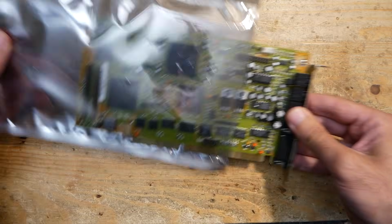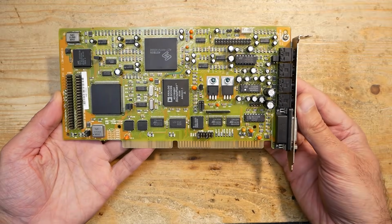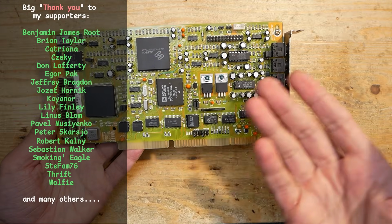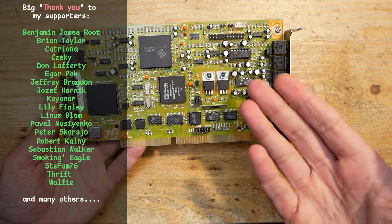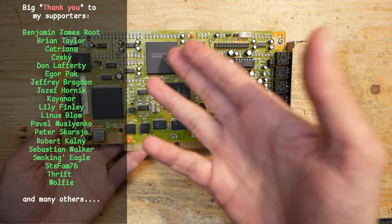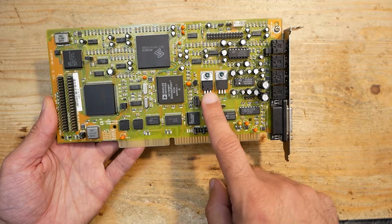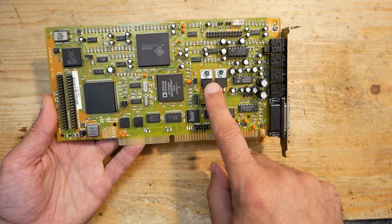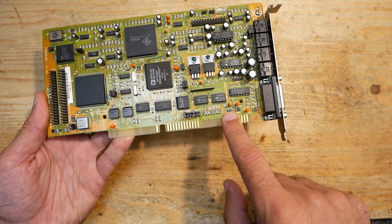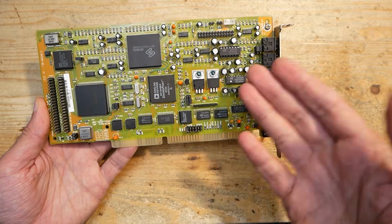Hello and welcome! In the last video I repaired this Aztech Sound Galaxy Basic 16 sound card, which turned out to be great for DOS gaming PC, since it is actually 3 different sound cards in one. A Sound Blaster Pro 2.0, Windows Sound System and Disney Sound Source. This sound card had a short and a previous owner removed both voltage regulators, probably trying to fix it. However, the short turned out to be in a capacitor and I was able to restore this card to a more or less original state.